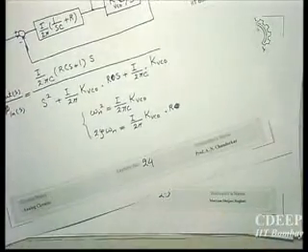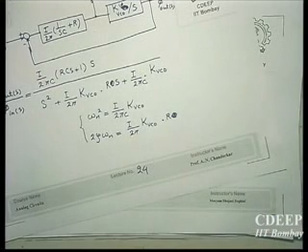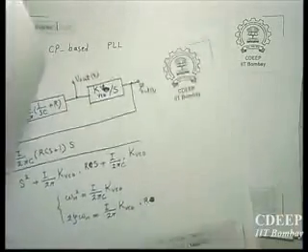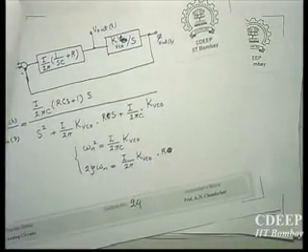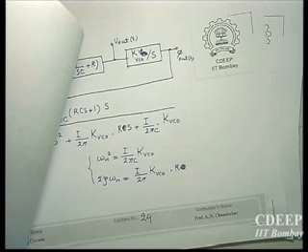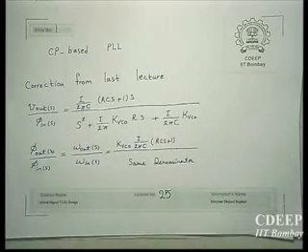So therefore, omega n square is I upon 2 pi C k VCO and 2 zeta omega n is I upon 2 pi k VCO into R. Okay, some literature use omega 0 instead of omega n. Therefore, if you see omega 0, it's same as omega n. Because in some literature, again, omega 0 is used for free running frequency of VCO. That's why I didn't use omega 0. And free running frequency of VCO is when input of VCO is 0. Center frequency. Okay, now we will continue.